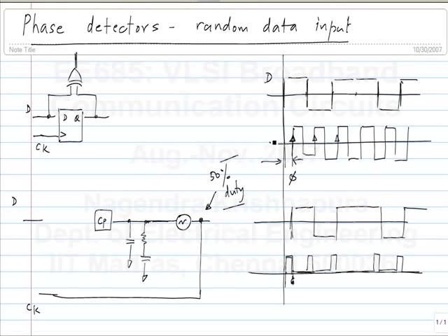It won't be exactly 50, but it will be more or less 50. Especially at high frequencies, you use an LC oscillator to make the VCO. When you use an LC oscillator, the waveform is almost sinusoidal. And if you have a sinusoidal waveform, it does have a 50% duty cycle, right? The successive edges are half period apart. That is, the rising edge is half period away from the falling edge and so on.